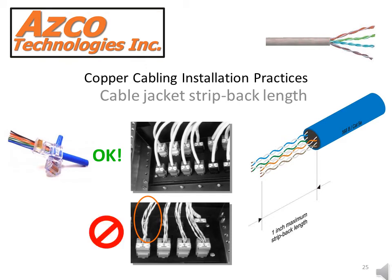The TIA 568-B.1 standard requires the installer to only remove as much of the cable sheath as necessary to terminate the cable onto the connecting hardware. It is recommended that no more than 1 inch of that outer sheath or jacket be stripped back.